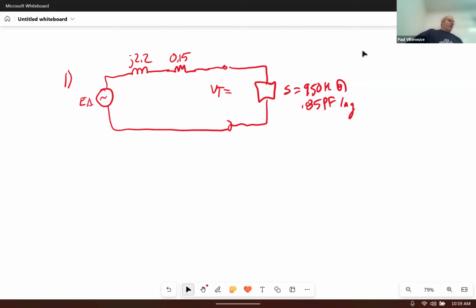Well, it tells you a 4.17 kV Y-connected synchronous generator, which means it's rated to deliver 4.17 kV, line to line. In three-phase, we have to do all of our work in single-phase equivalent. So you needed to divide that by the square root of 3, and then you set it at an angle of 0. That was the first thing, and pretty much the only thing that you needed to do.